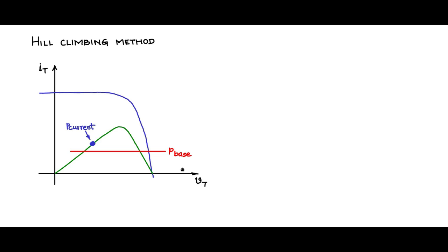We saw as an example, in the case of a buck boost converter, the load line along the horizontal x-axis is D equal to 0. The load line along the vertical y-axis is D equal to 1. So if I swing D from 0 to 1, you will see that the operating point moves and the operating power point also moves like that. So let us say D is increasing. So the operating point will be moving to the left. So let us say it moves to the left like this.